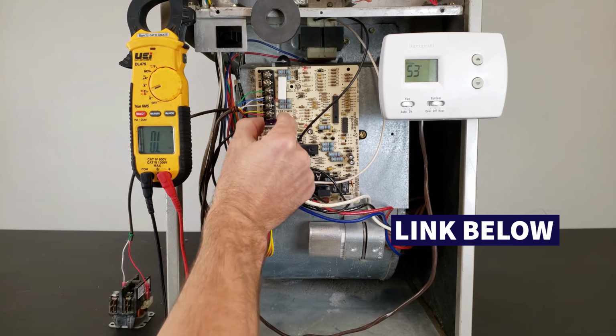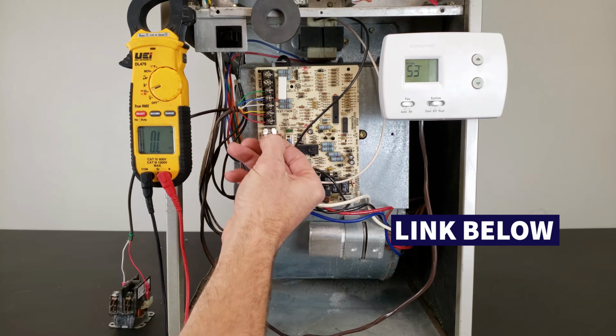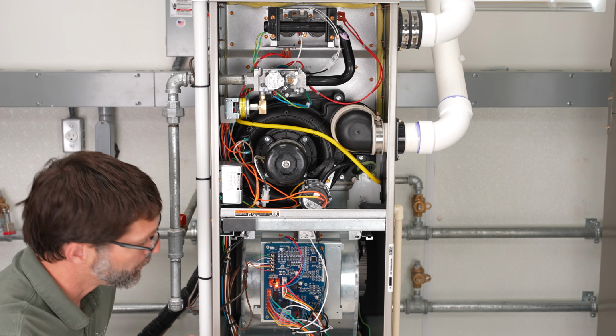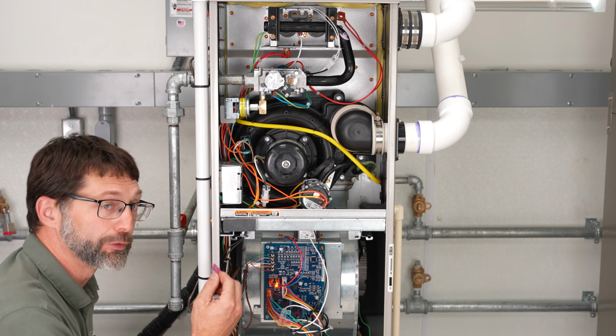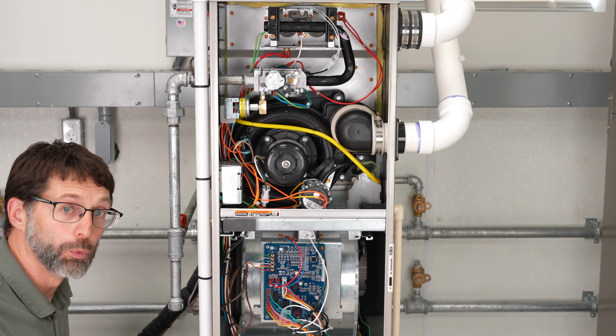But basically we have a whole other video on how to find low voltage shorts down in the description section below, but you use your multimeter with electrical resistance in order to determine where the problem is. You don't just keep putting in fuse after fuse and watching them blow. So you have to really diagnose that with your multimeter.